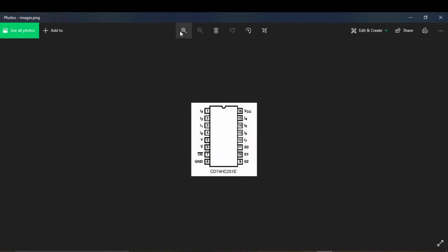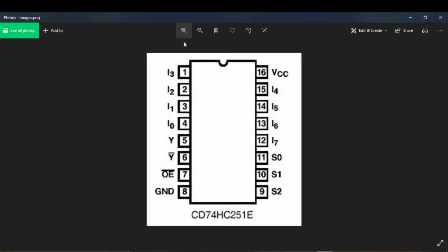Here you will see that these will be the selection lines. The other 3 inputs of the sensors that we have not compared with the output of the motor in the rudimentary logic, we will just use as the selection lines. These are the 4 inputs here and the 4 here. So this is called an 8 cross 1 mux, in which the voltage at here and the ground at here will be applied, and the output at the 5th terminal of this IC will be obtained.